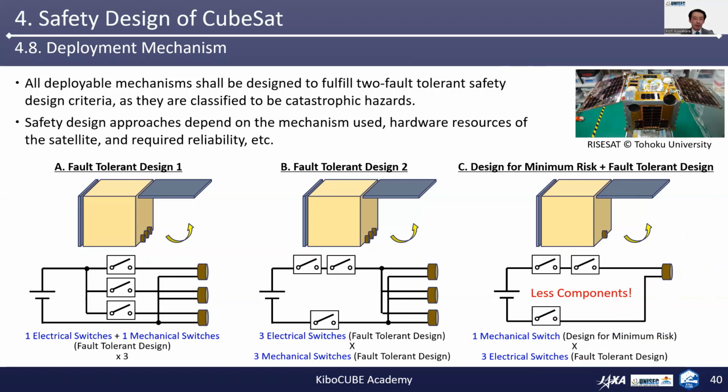From the electrical point of view, you will still need 3 switches for the fault-tolerant design, but in this way, we can reduce the required components from 6 down to 4. I hope these examples also gave you a hint about efficient and strategic safety design of your satellite.